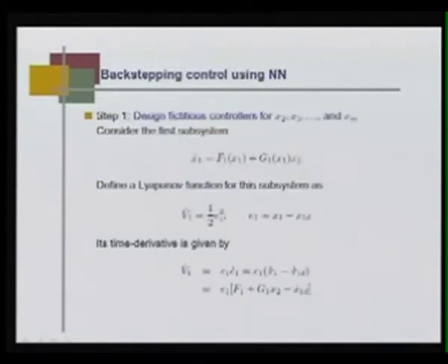So, now backstepping control using neural network. This is the theme of this particular class today. So, I introduced what is backstepping control. Now, we will go into detailed design using neural network. Design fictitious controllers for x2, x3 and xm, first step.